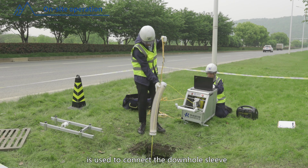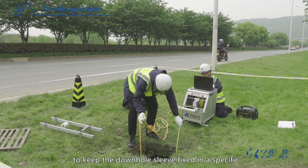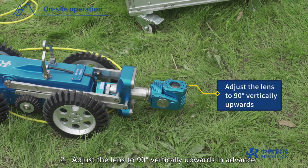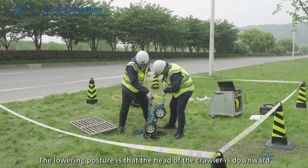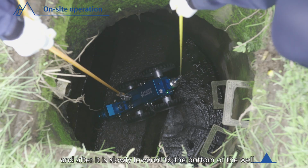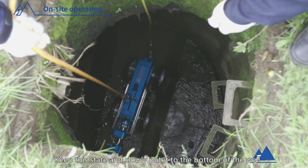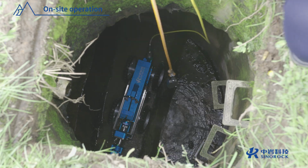Another safety rope is used to connect the downhole sleeve to the surrounding fixtures, to keep the downhole sleeve fixed in a specific position and prevent excessive wear of the cable. 2. Adjust the lens to 90 degrees vertically upwards in advance to prevent bumping the lens when going down the well. The lowering posture is that the head of the crawler is downward and the tail of the crawler is upward, and after it is slowly lowered to the bottom of the well, the crawler is adjusted to a horizontal state and the crawler is parallel to the pipeline. Keep this state and slowly put it to the bottom of the well. Loosen the hook to recover the safety rope.